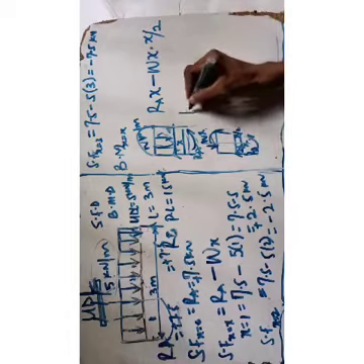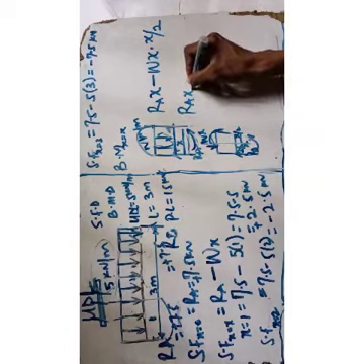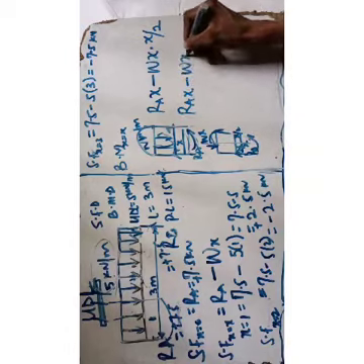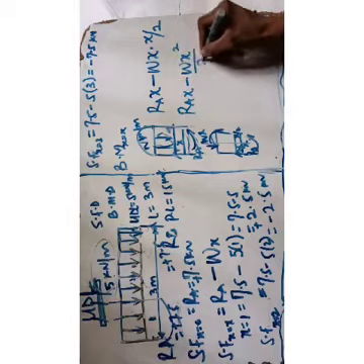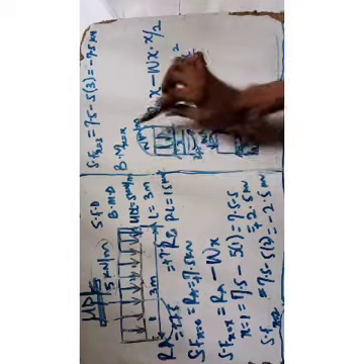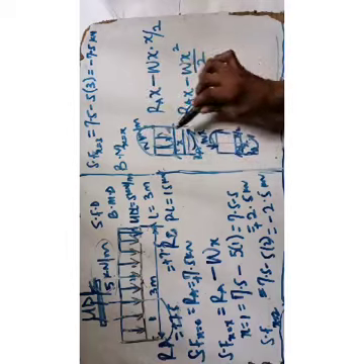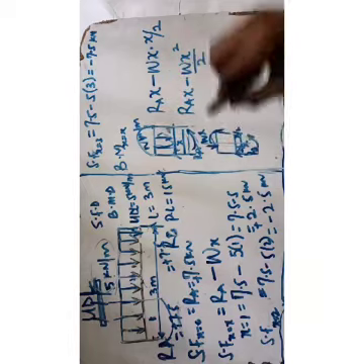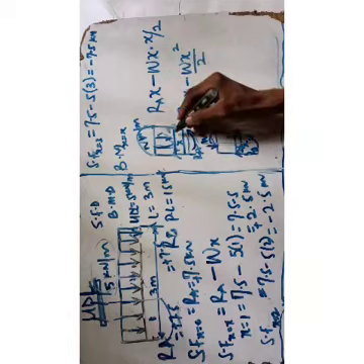Okay, so therefore that will be RAX minus WX square over 2. What do I do? What I did as well is that you will first of all convert to point load. So that is area, length times breadth. That is WX. When you convert this to point load, it will always act, the gravity will always act at the center. Then you have your x over 2, x over 2.